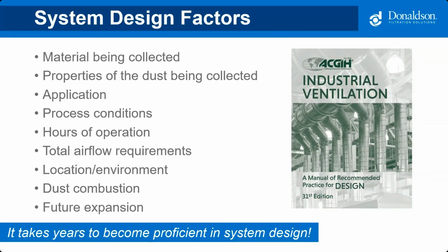Do they have compressed air available? Does the collector need to be located indoors or outdoors? What's the footprint and height requirements to make sure it can fit? Has the dust been tested for combustion or flammability? If it is, what are the NFPA standards that apply? And does the plant have expansion needs that we should consider when we first design the system? So as you can see, there's a lot that goes into designing a system.